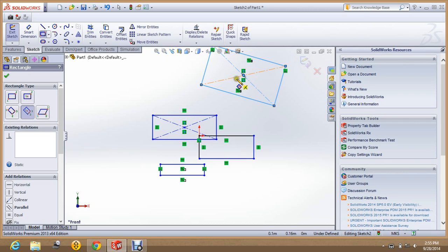You just click first the center, then one more point, and then again a third point. So it will generate the rectangle based on the selection of 2 points. These 2 points I have selected, that will be collinear points, the last 2 points.